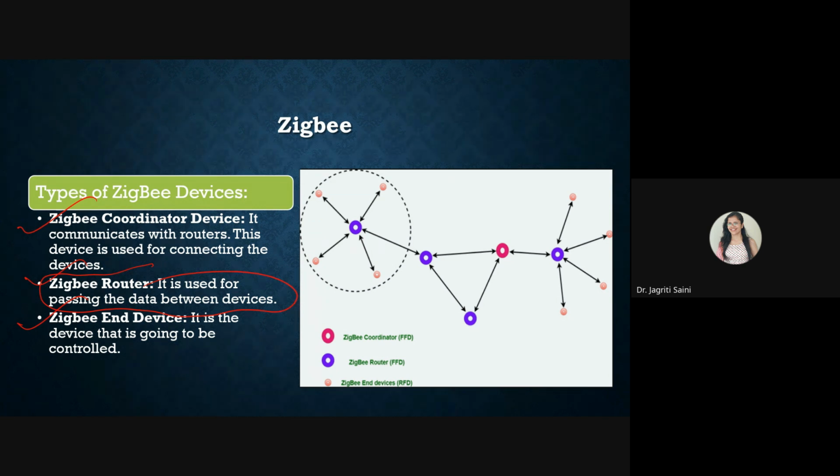So you can get a router to set up communication to the next floor, and then on the other floor also, again you can set up multiple routers, multiple coordinators and end devices, and then again on the floor above it you can again use a router to send data, and that will be a hop based communication. So if it can cover like a minimum range with the one connection, the routers can further extend it and pass data with better connectivity between different units.